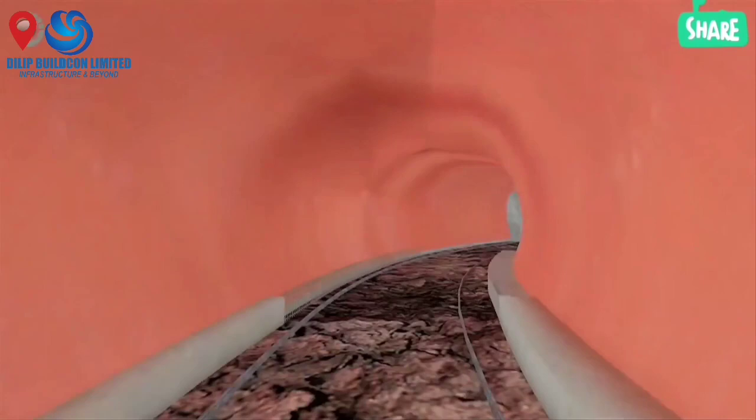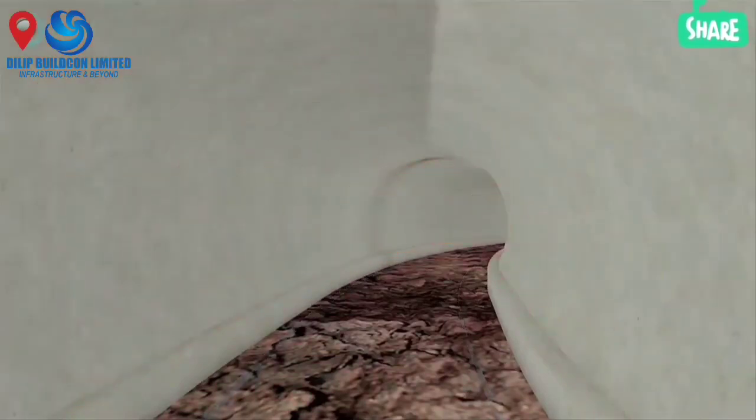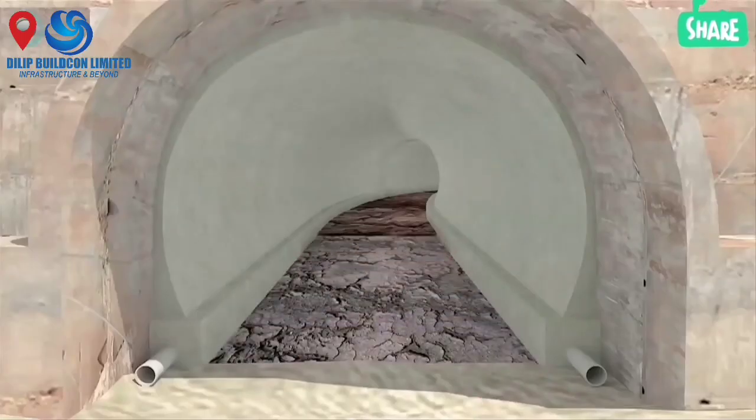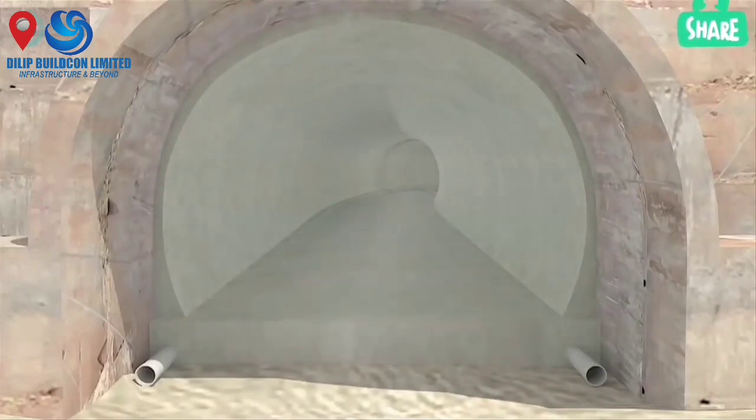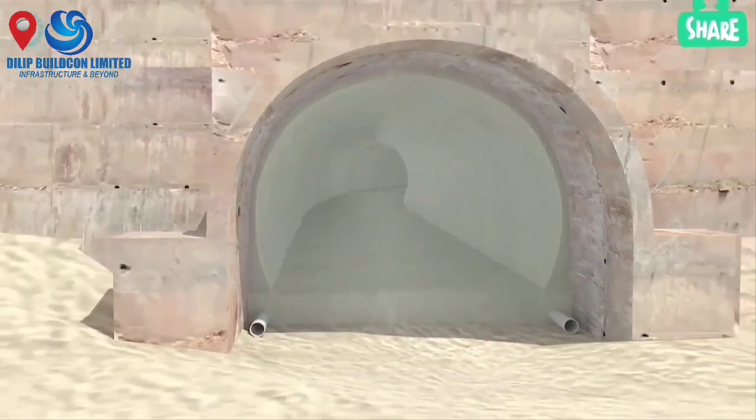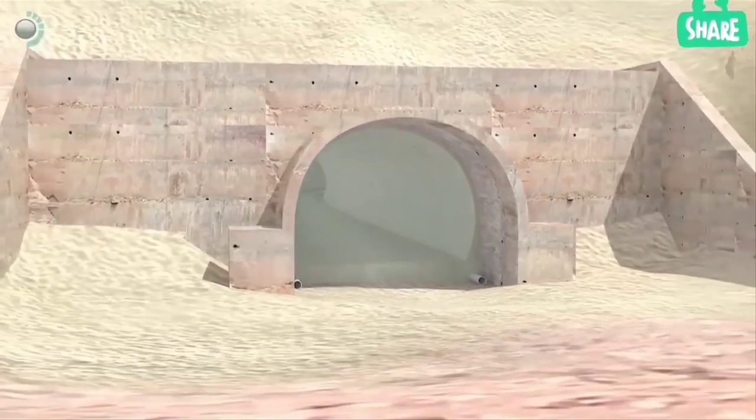Once the entire tunnel is completed, the kicker gantry and main gantry are dismantled. After that, the floor is washed and cleaned. RCC concrete is poured. In this way, kicker arch and invert concreting are completed. All the portals are finally stabilized with